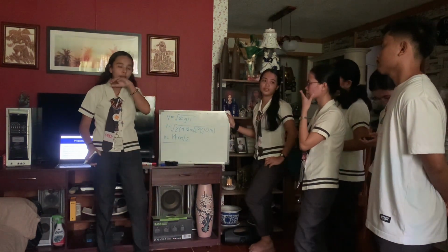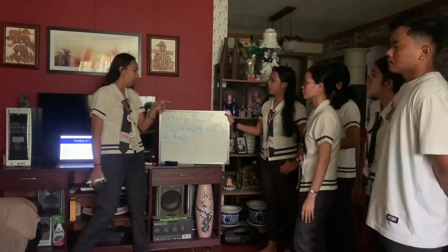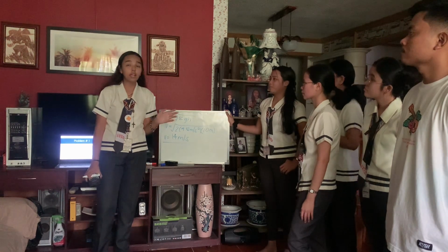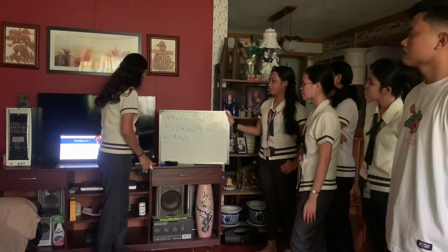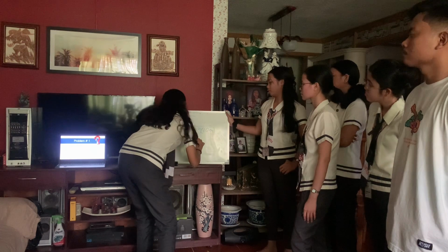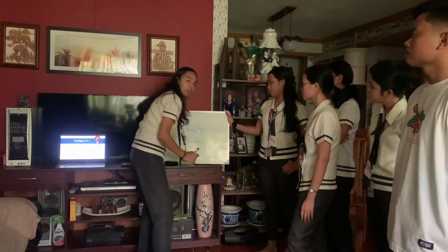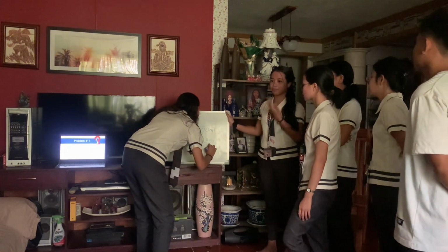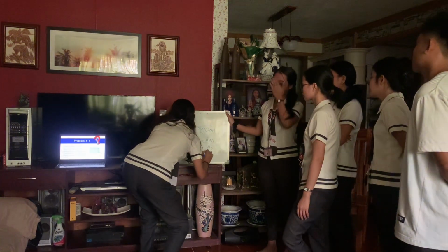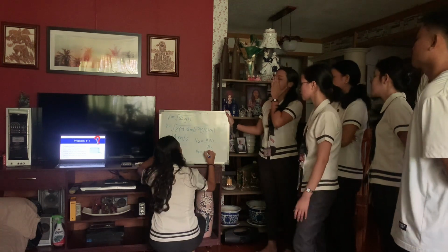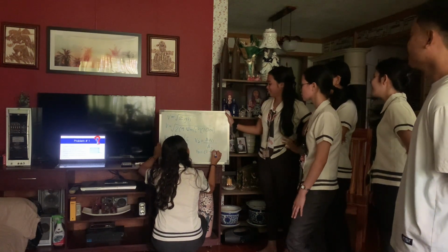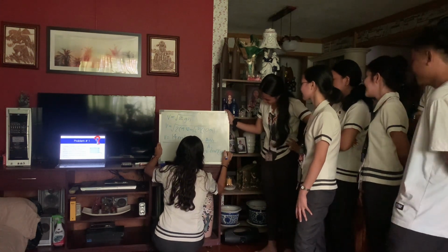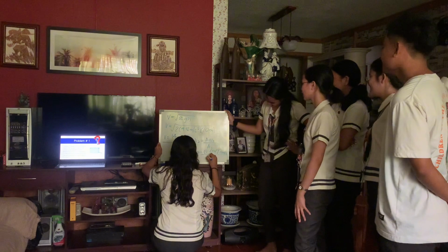Earlier, we assumed that V2, the velocity at the top, where the cross-sectional area is large, is 0. So let me prove that it is 0. V2 is equals to, using the continuity equation, A1 times V1 divided by A2. The area 1 is 0.01 times 14 meter per second divided by 1.